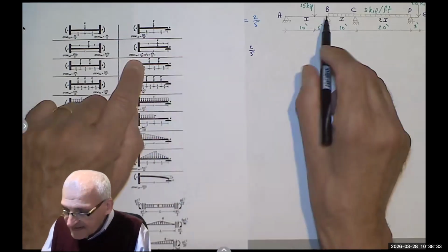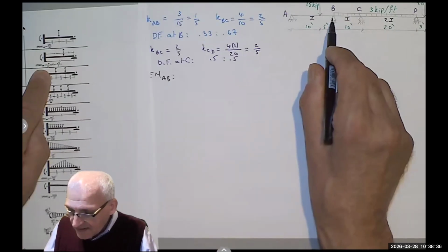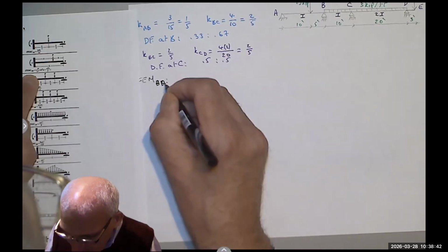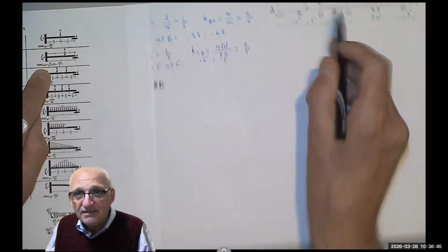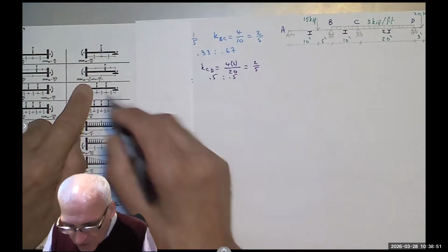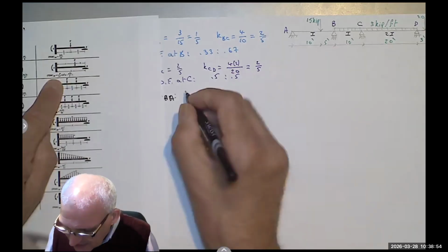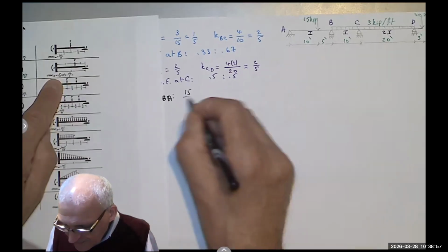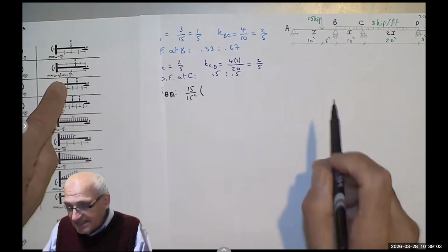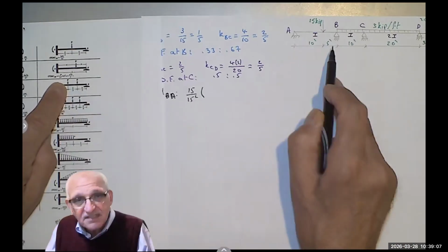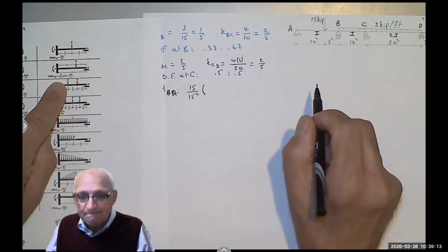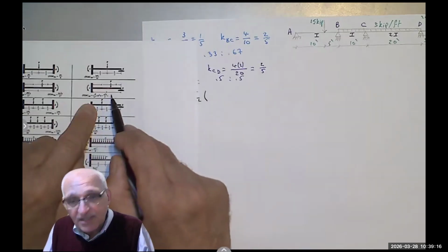And it tells me that the fixed end moment at B, in fact, I should say BA, AB is 0, right? That's a pin. So BA, or sometimes I prefer to call it B left and B right. So I can say fixed end moment B left equals P over L squared. Well, P is 15, L is 15, so over 15 squared, times B squared A, this is A, this is B. So A is 10, B is 5. B squared A plus A squared B over 2.